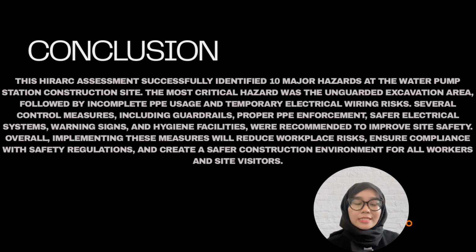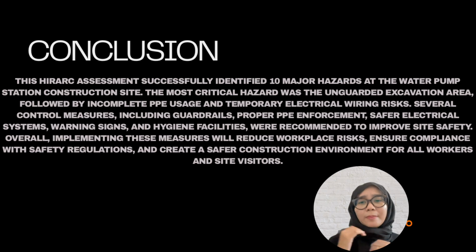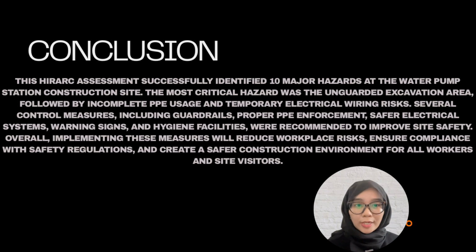So last but not least, in conclusion, the HIRARC assessment conducted at the water pump station construction site in Universiti Tun Hussein Onn Malaysia successfully identified 10 major hazards and health risks associated with construction activities. The risk assessment results showed that the most critical hazards were unguarded excavation works, inadequate implementation of personal protective equipment, and the risk of electrical fire from temporary wiring.